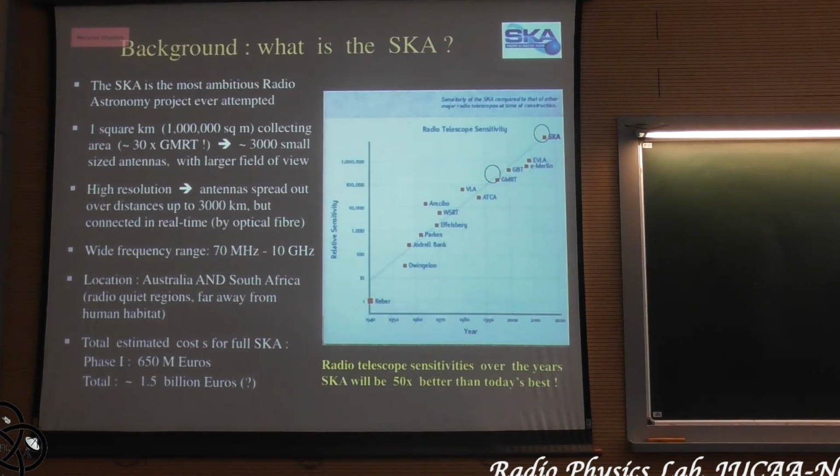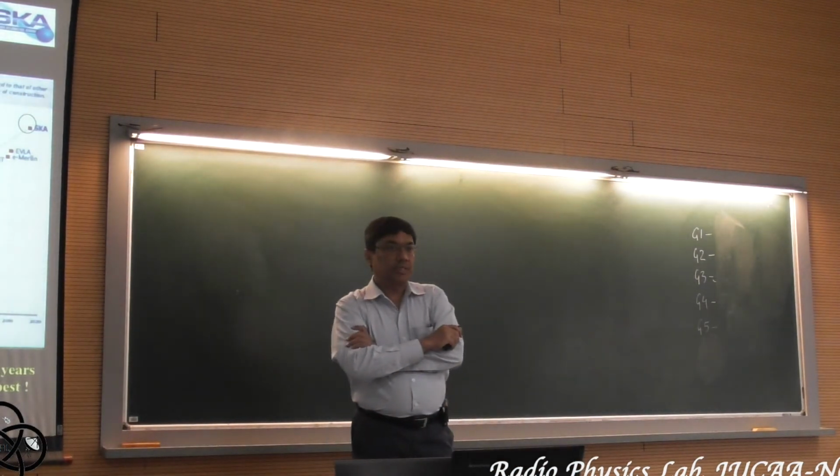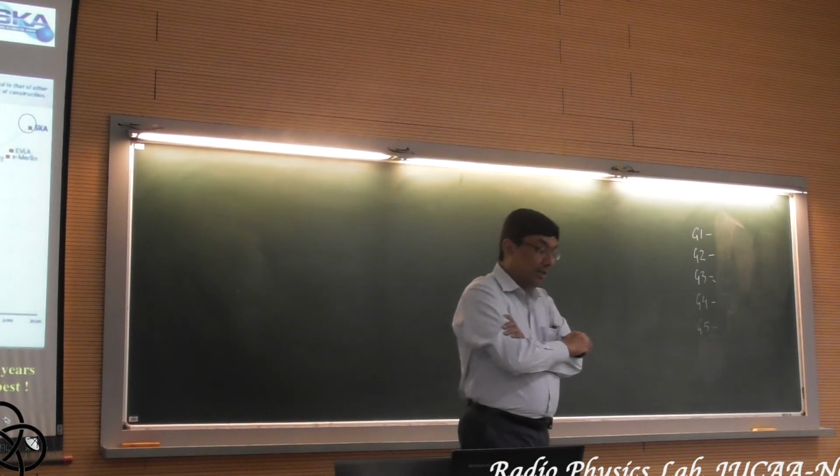Again, the location. One of the big problems that we have in GMRT is the man-made interference, which I talked about, which comes from whether it's your cell phones or your TV channels or the aircraft flying over or any other man-made activity, any sparking activity. If you take your petrol-driven vehicle near the GMRT antenna, it will see the sparks which are picked up by the antenna, and so on. So you try to put these as far away as possible from man-made activity, but still within reasonable reach, so that you can go build it, maintain it, and run it, and get data from it.